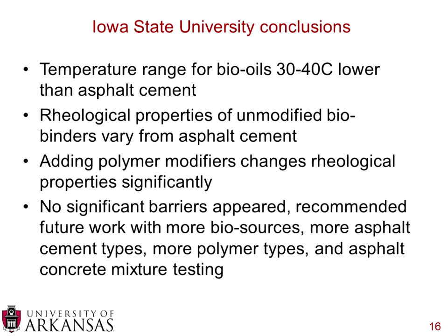They also played around a little bit with adding polymer modifiers to the biobinders. So they're taking these 100% biobinders and then adding polymer modifiers, and that significantly changed the rheological properties, and in some cases it actually improved them. So I think that using 100% unmodified biobinders may not be realistic at this point, but perhaps blending it with some other materials can help increase the potential for them.